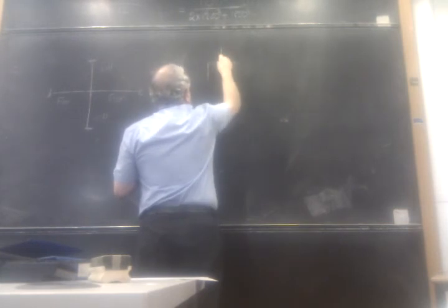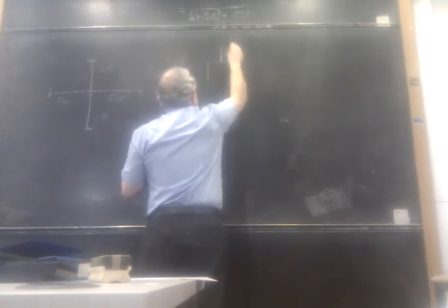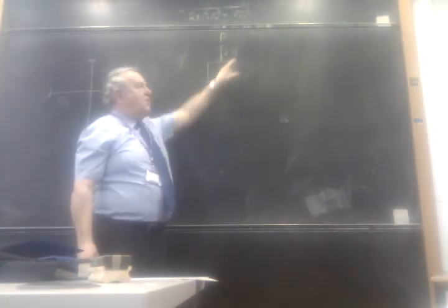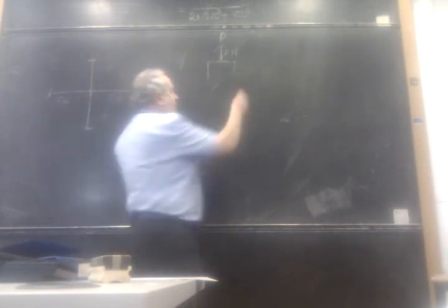So we're going to try and calculate the bending moment there. And if we know the bending moment and we know the vertical load coming down, as far as our cross-section is concerned, we'll have an M and a P. So what we want to do is calculate the M, because once we've got the M, we can determine the eccentricity.